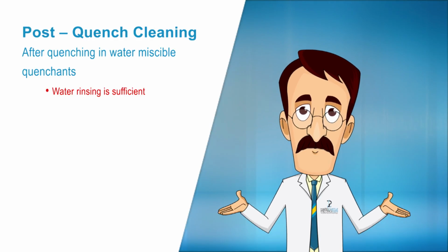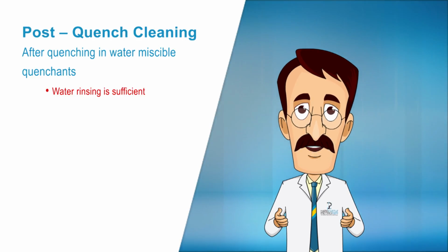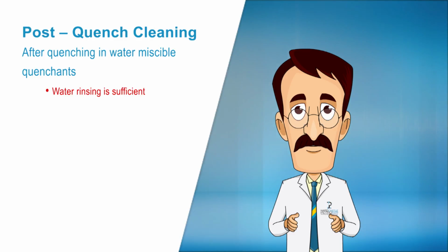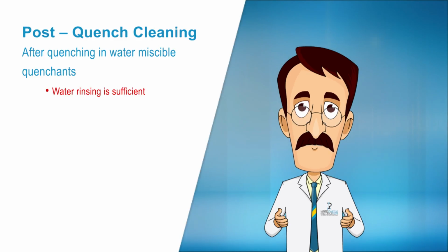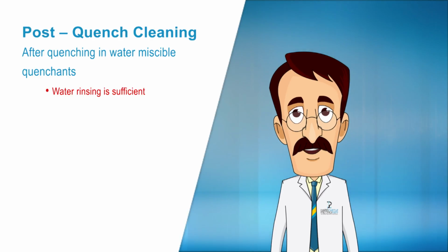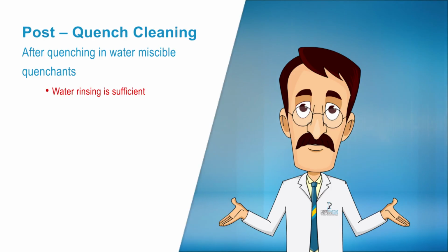Hardcastle Petrofer's quenching oils will produce hardened components with a bright finish, provided, of course, there was no prior surface oxidation. The components are suitable for further treatment, such as electroplating, without problems. Oil residues do not burn into the surface of the metal and therefore can be easily removed.